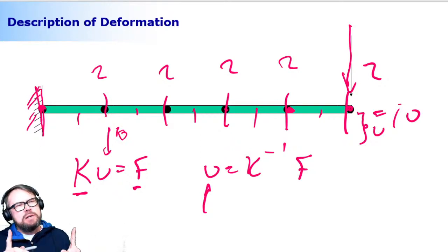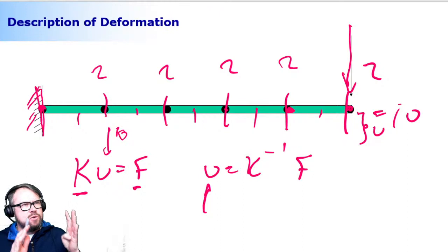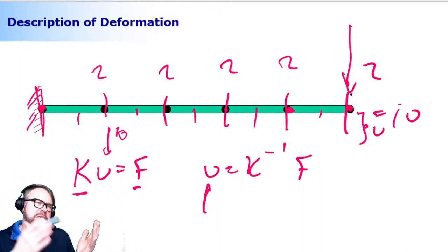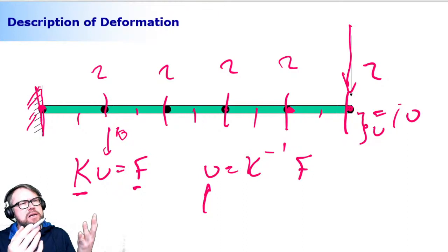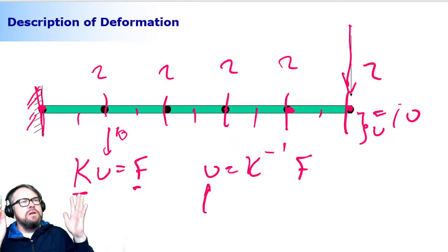I could do this a little bit differently. I could first conduct an eigenvalue analysis of this cantilever beam. An eigenvalue analysis means that I'm looking at the ways the structure can vibrate. Maybe it would be easier to say the ways that the structure can deform. How much they can deform in that particular way will remain unknown for us. That's going to be called something like an amplification factor, and we're going to solve the amplification factor instead of the nodal degrees of freedom.